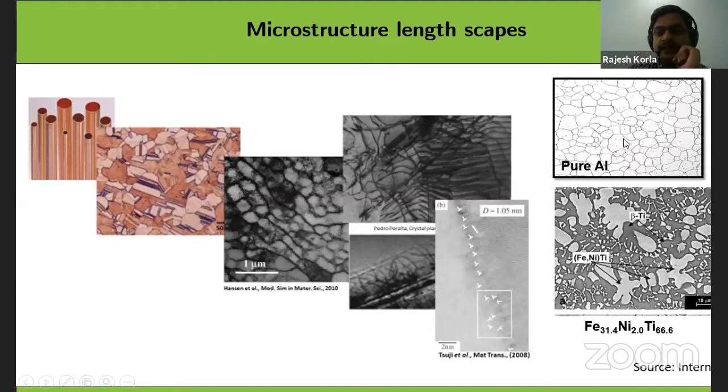On top of that, there is a pure material, where all the grains have the same phase, and there is a two-phase structure, where the composition partition and the crystal structure of the two phases will be different. Then the mechanical properties of the two phases are different, and when you apply a macroscopic load, the strain partition between the phases can be different. To model the macroscopic load, you should know the individual mechanical properties of the individual phases, which you can't do in a conventional uniaxial tension machine, right?